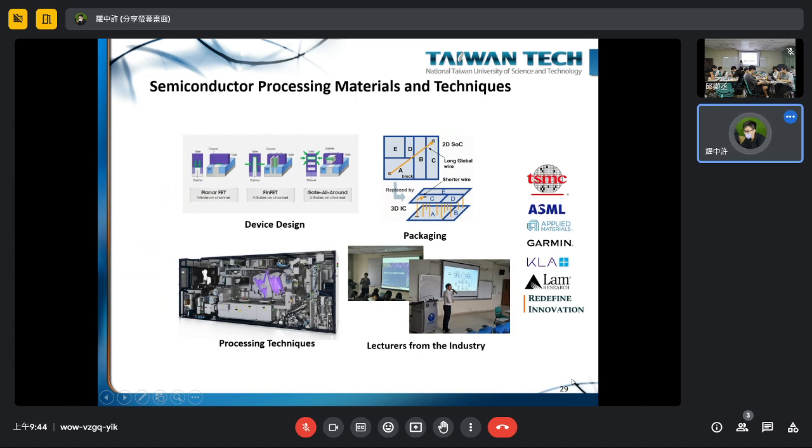You try to reduce that, so you make shorter wires, because wire means energy dissipation. After you play a game, the power disappears. You try to make an IC with lower energy dissipation so you can play your game longer, right? So you use 3D IC. That's the point of why we need to go from 2D to 3D packaging.